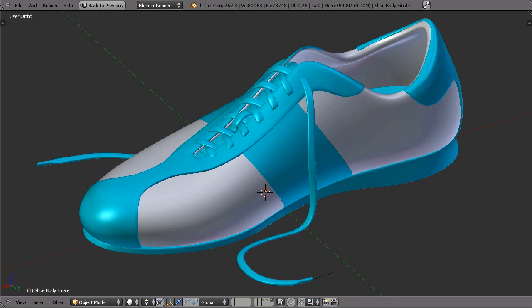My name is Claas Kuhnen and today I'm going to give you a quick run through how you could model the shoe with Blender. Before we start modeling, I would like to spend a moment setting up the scene. First, I'm going to place background images into different views like top, bottom and side view. This will help serve as a blueprint for referencing proportions.